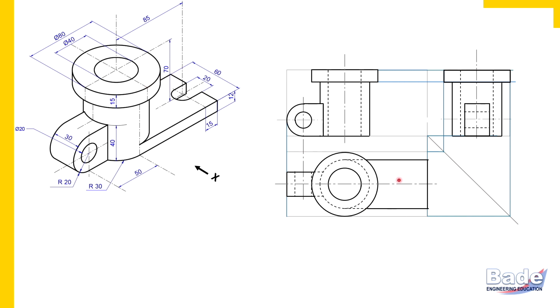So this edge on the front side and the corresponding edge on the back side, under this circle we have shown dotted. Like the U-shaped block, this plate also comes in contact with the cylindrical surface. It is attached to the cylindrical surface, this cylinder. So let's show that attachment properly. Otherwise, in the front view, it is simply a rectangular strip.